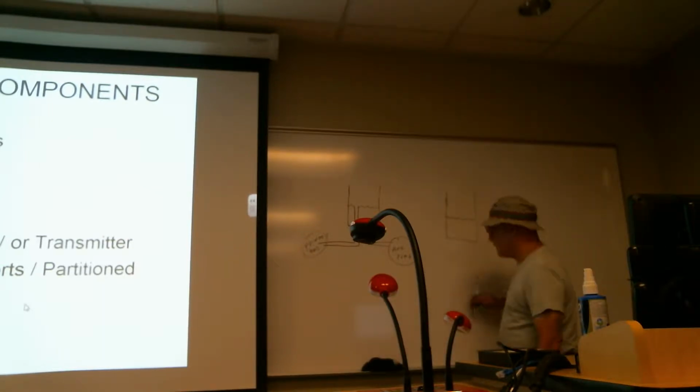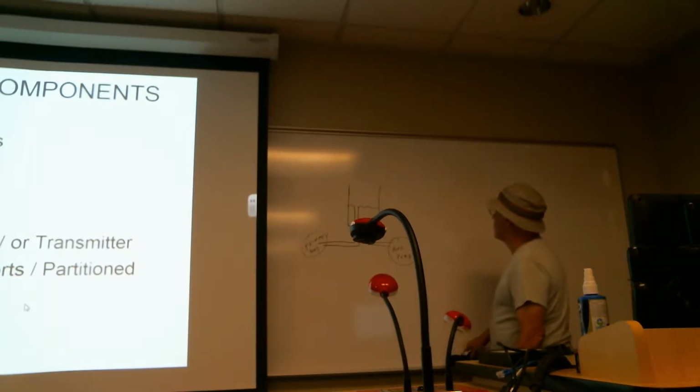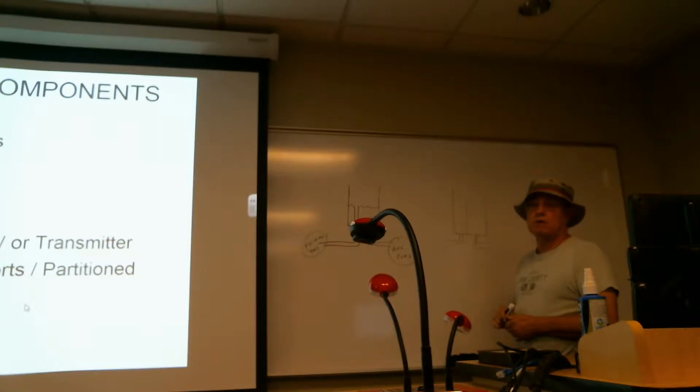Another way that we can kind of provide for maybe reserve fluid is just to have a partition in the reservoir. So you might have a wall that's been built up in the reservoir, and again, it does the same thing. One side of the wall feeds a power pump, the other side of the wall feeds an emergency pump.